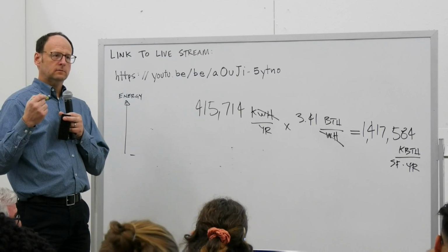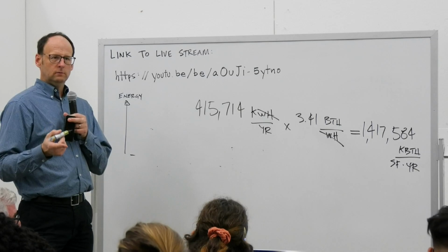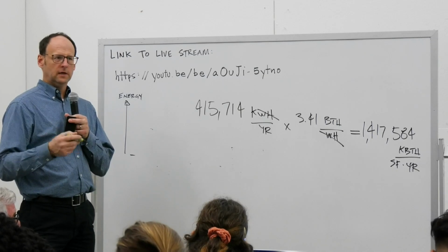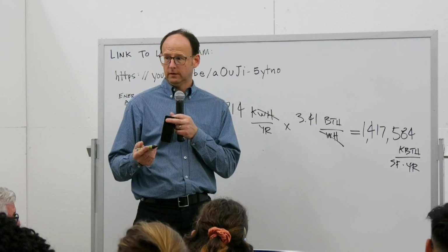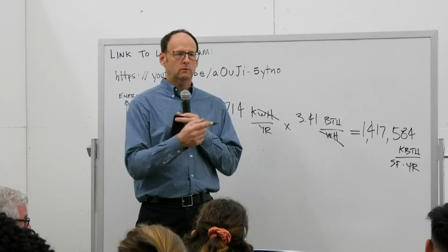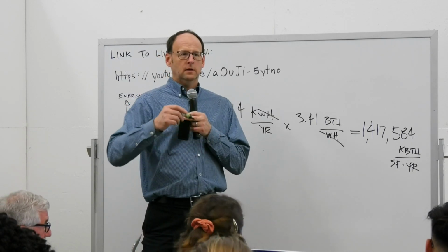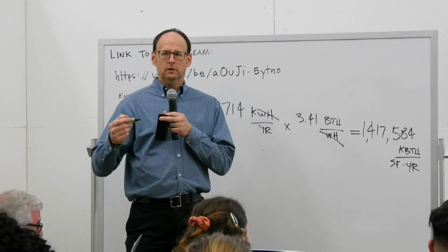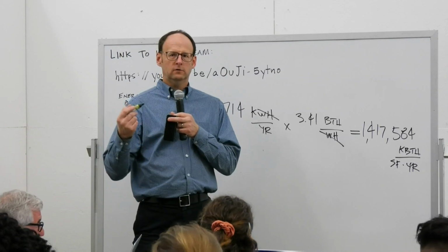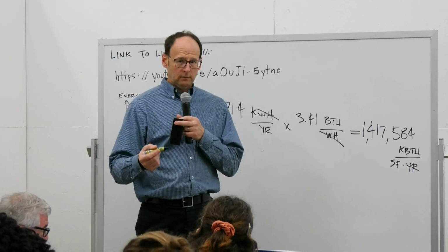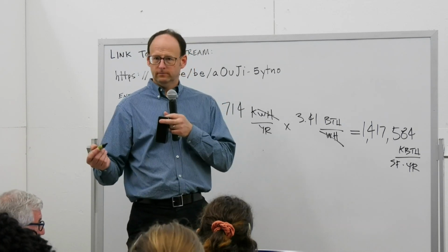Bill also gave us some different energy intensities for different buildings. Do you remember what he said was the approximate energy intensity in kBTUs per square foot for a school? It's around 25. Do you recall that? And he did a restaurant that was around 150. So we're going to calculate how much energy a school with an EUI of 25 and a restaurant with an EUI of 150 need in a year.